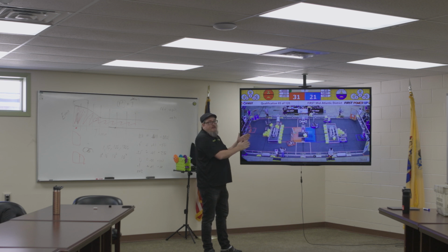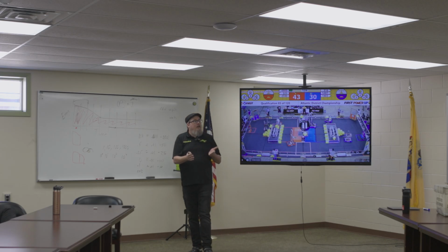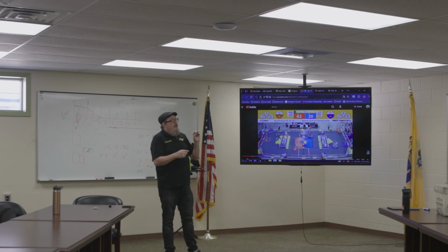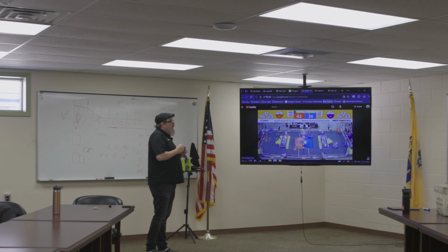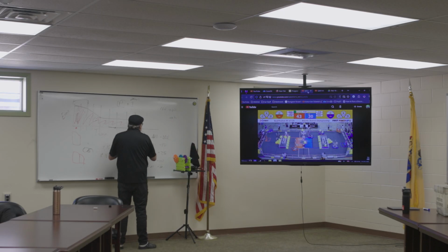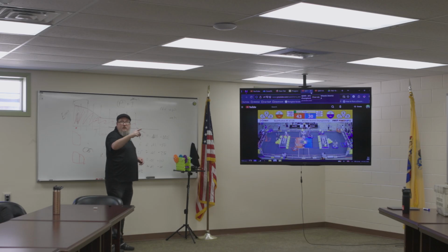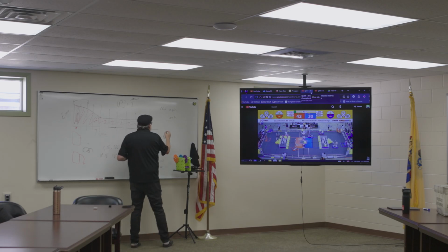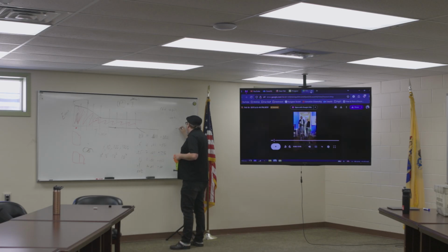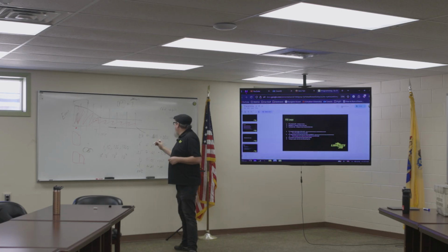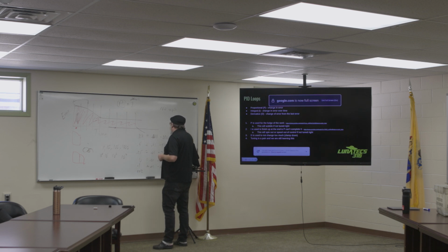What happened when I overshot the target? It wobbled back. Why did it do that? Because it was trying to align with its target, but it did that automatically. What happens if I dip below this line? It has to go in reverse. Why? Well, it has to subtract power from it. So if my error is -100, and I multiply that by 0.001, I get -10%.